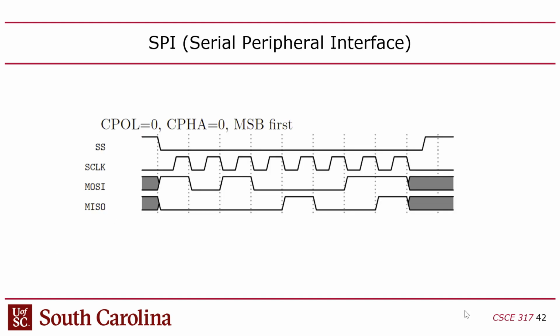Okay, so let's look at some examples of this now. One of the things we want to convey in this course is how to read timing diagrams, and how to interpret signal traces and see how that corresponds to the transactions between devices. So this is a timing diagram, and the horizontal axis represents time. You've got your 4 signals here, and each one is shown as a binary value that can be high or low, on its own vertical axis.